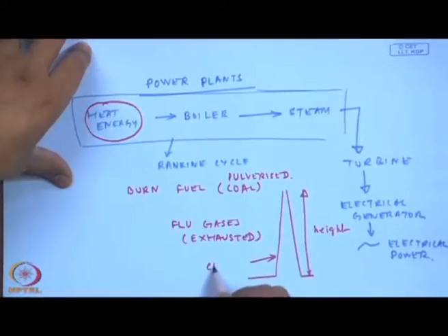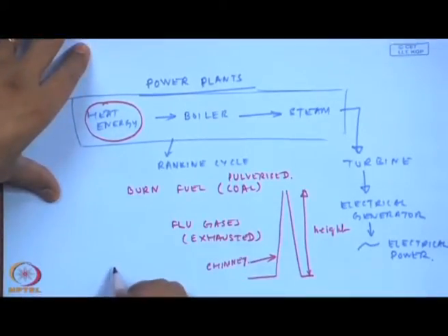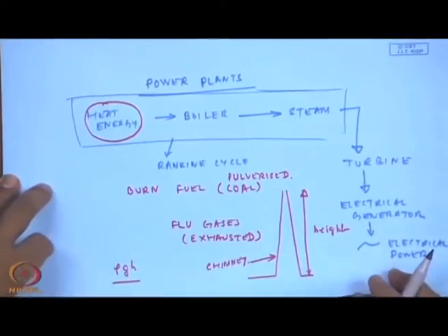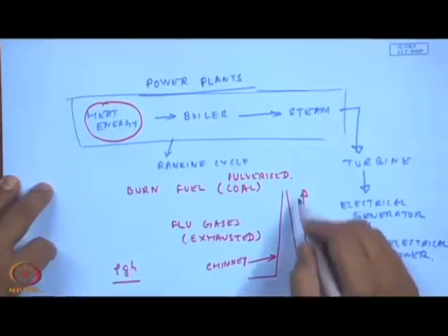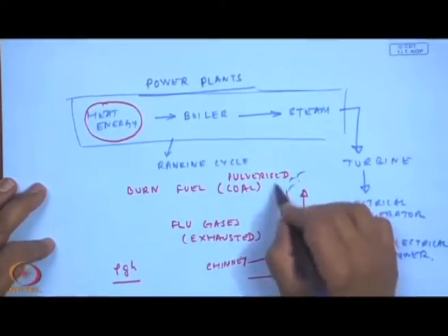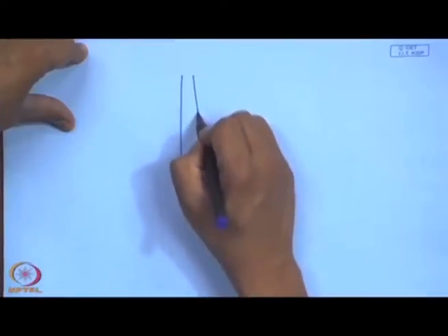and this is the chimney, okay. And the rho g h is the pressure head. So, obviously, this height has to be maintained, because we do not want these gases to be coming out of places where they could be harmful to people. So, they have to be given a certain energy, so that they can all go out that draft height of the chimney.